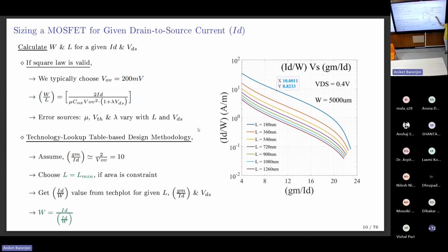So what do you think the percentage error will be? The percentage error will be nil. Why? Because I kind of hacked the system to get the device characteristics upfront, and I'm now using the same device characteristics to get the device. So there's no way that will go wrong. I'll share with you how a little bit of source of error can come in and how to fix it. But for now, we're together, right?